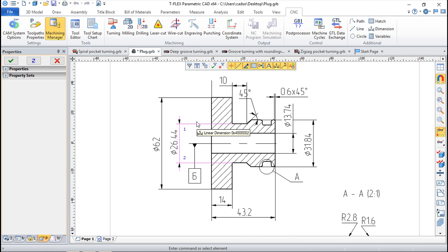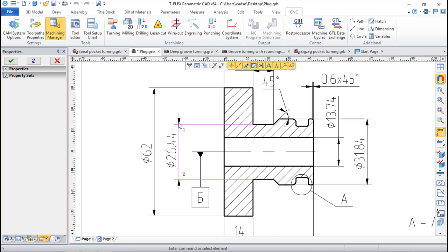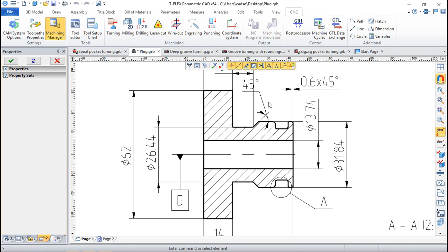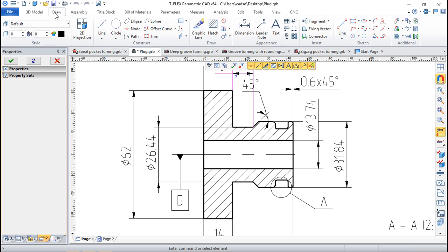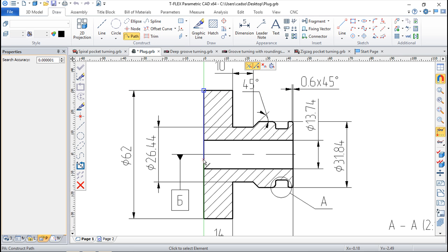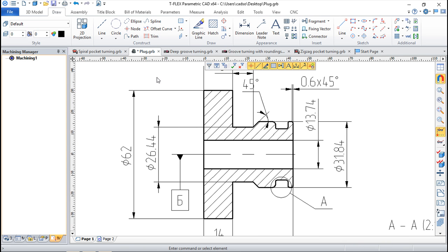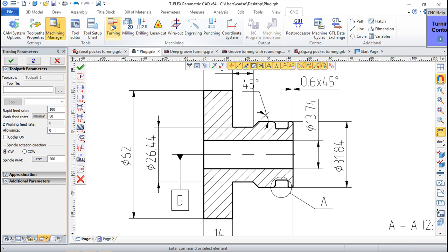For that I have a couple of files to show you the main examples, and I have still the same file I've used in part 1 to show you the cutoff, and the cutoff will require a path. So draw, and in this particular case path, I will create one here, and that's it. And the cutoff, it's a very simple toolpath, because the purpose is to divide or to split the final part from the block that was started to make the part.